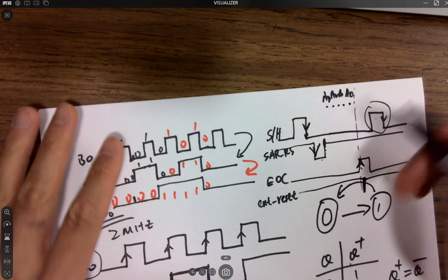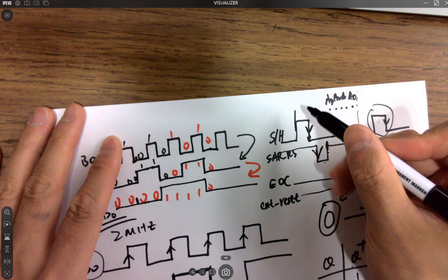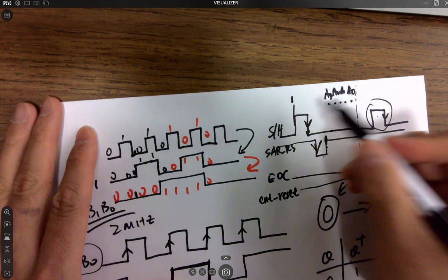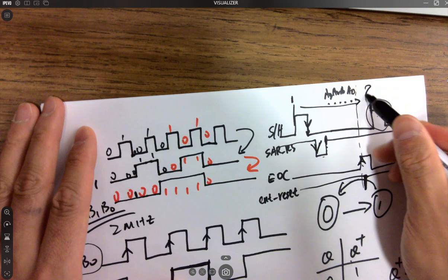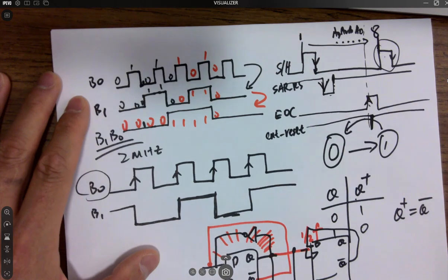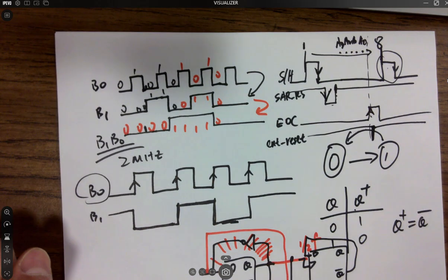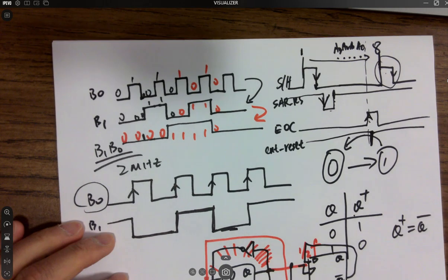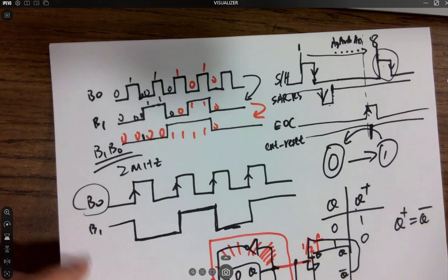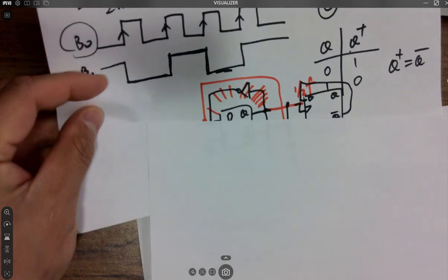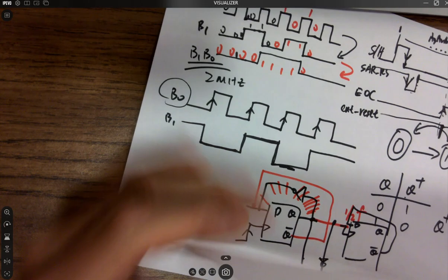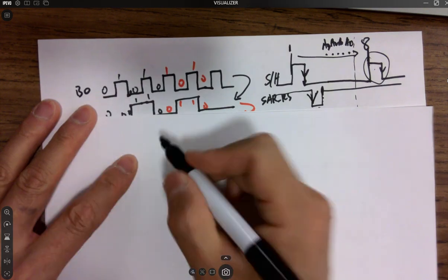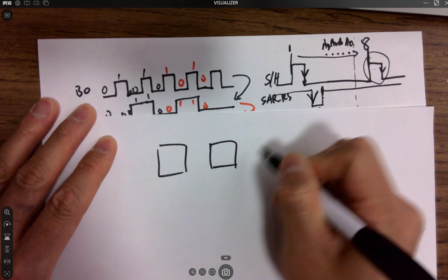Okay. So for example, from here, it's probably not the right number, but from here it counts 1, starts counting 1, to this point is number 8. And for number 8, I want to reset the counter. How would you like to design the circuit to count to 8 for 4 bits of D flip-flops? I guess I need a reset. So you have 4 bits, and you have to reset it.